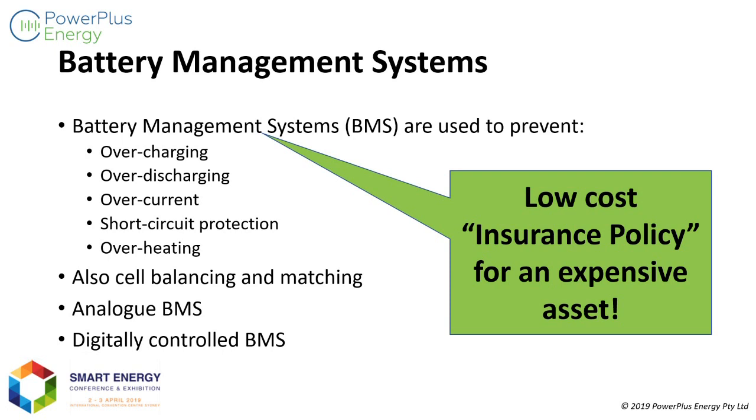I brought along with me one of the battery management boards that I designed recently for our batteries. This is a 120 volt lithium battery management system. It's been designed to be particularly thin in this direction to be able to fit into a 2 rack unit rack mount case. So basically what we've done is we've taken the equivalent of a car battery management system and squished it into 3 circuit boards this size. It took a lot of mucking around, but we eventually managed to do it.